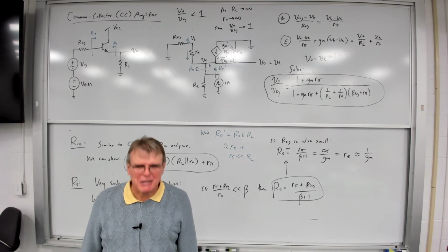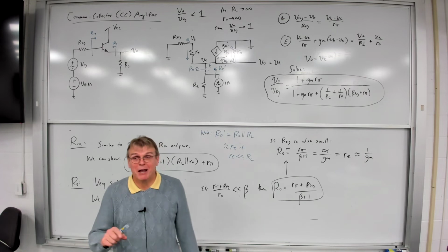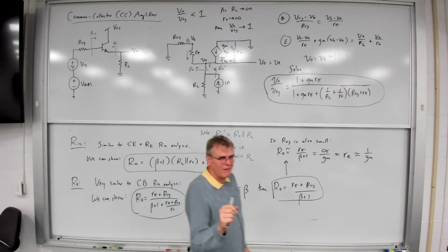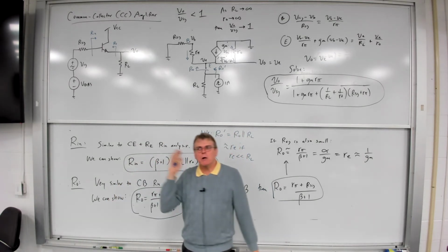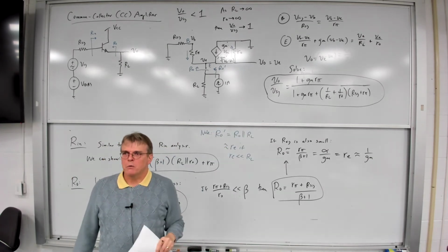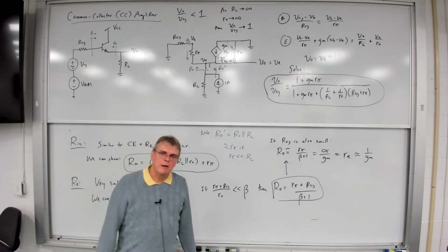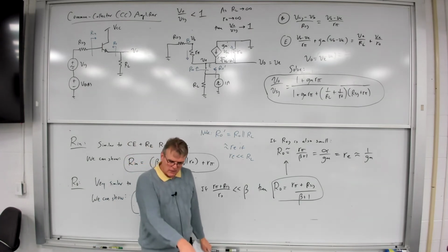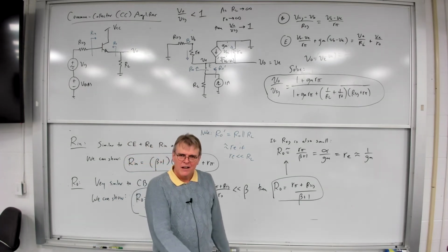It should be a minus 53, right? Shouldn't a common emitter amplifier be an inverting amplifier? Yeah, okay. So that's what I want you guys to think about. Think about the general properties that come out of these equations. It's a way of looking at your numerical answer on an exam and saying, okay, does that make sense? All right.